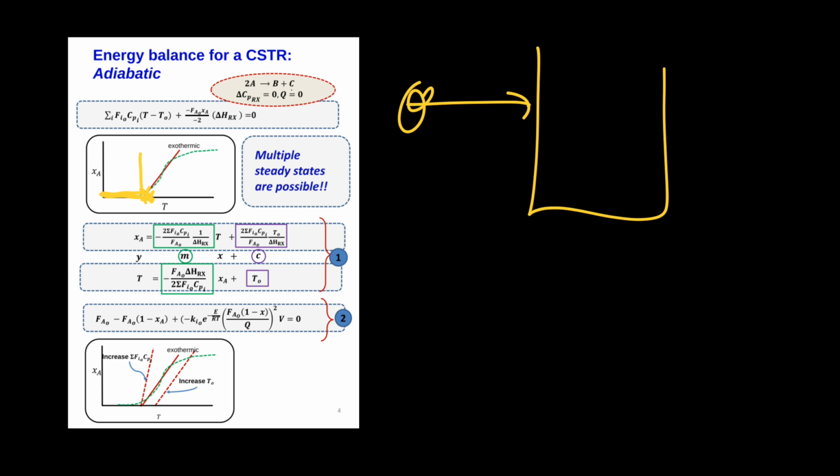So what can actually happen in your reactor is you can happily be operating at the optimal high steady state, high conversion condition. Then there's a sudden drop in the flow rate. Suddenly there's a discontinuity, something happens in an upstream vessel. So just for a moment, the volumetric flow rate drops and then it comes back online again, and suddenly you find yourself operating over there. Not that suddenly, after a while online, but you operate at a much lower conversion. And the explanation is that this is actually a steady operating state for that system.